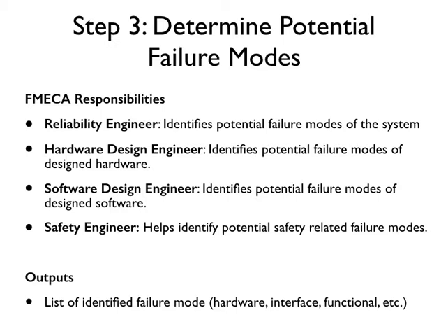And the safety engineer, because of the way that they perform their assessments, they have a variety of hazard analyses, which in a lot of ways are very similar to a FMEA or a FMECA. And so they may also have some failure modes that should be included in the analysis. So that's a good position to bring in when developing these. The output of this step then would be a list of failure modes, a total list, but it might be a list for the particular components, or maybe it's by function. But the goal at this step, of course, is to develop the entire list of failure modes.